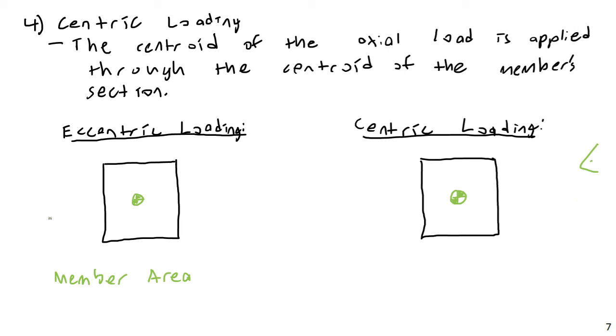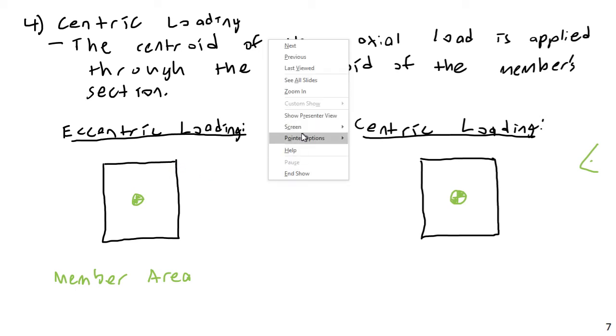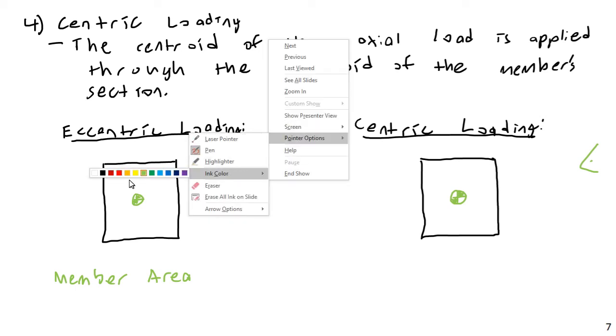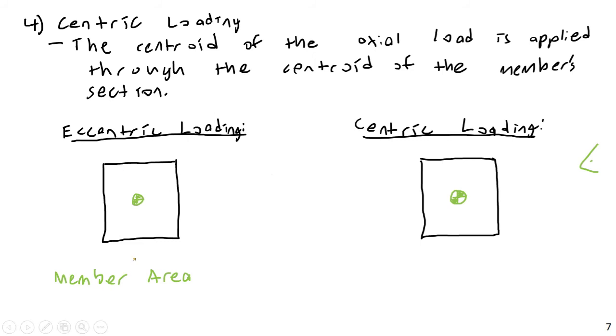But anyway, now in another color, I want to show where the load would be applied. So when we draw things as point forces, we draw them as idealized forces where they're all acting through a single point. But we know that's completely impossible. I can't actually apply a force to a single point. Usually that's a decent assumption, especially if something is applied over a couple inches and we're looking at a member measured in many feet, a point load is a reasonable assumption.